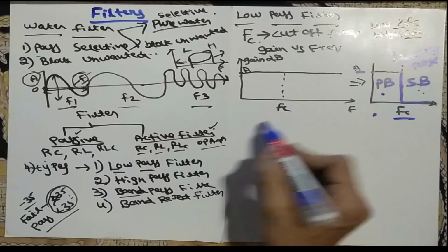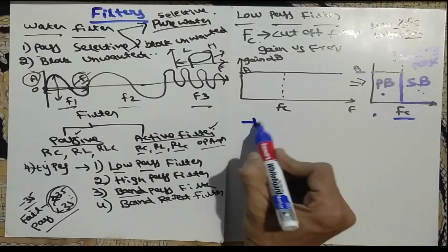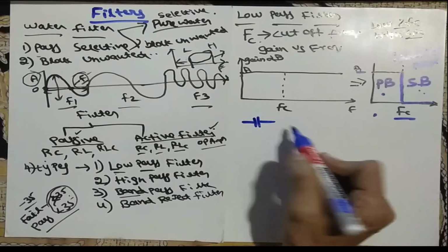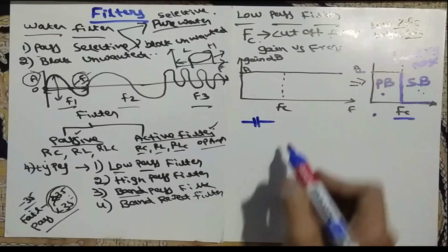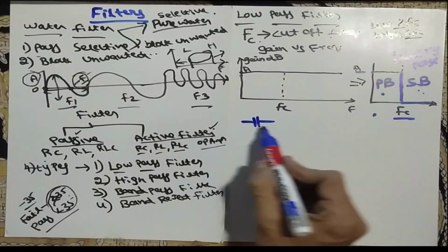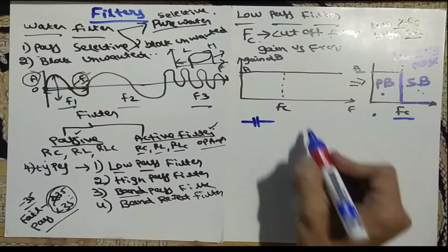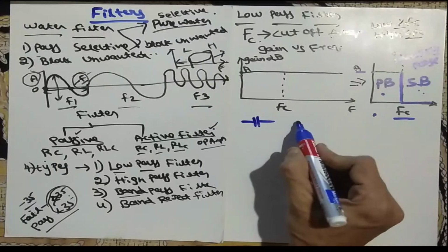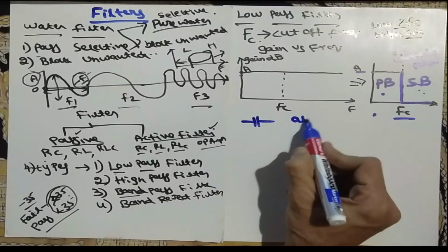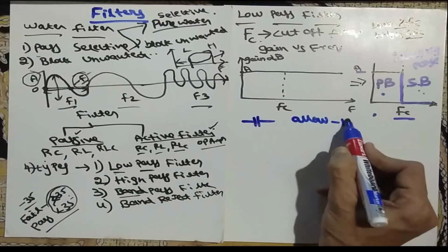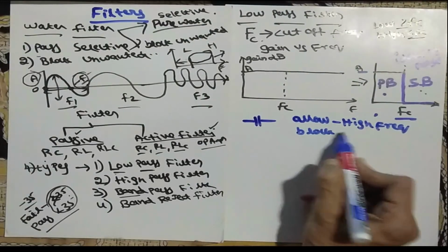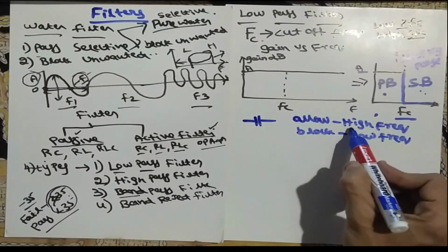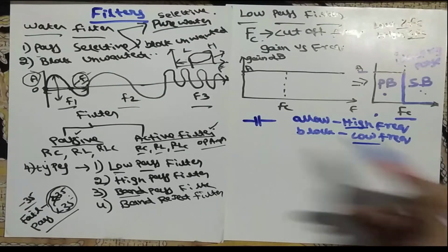Usually, if you take a capacitor, what is the operation of a capacitor? We know that in DC it blocks, and in AC it allows, but usually in AC it will not allow all the AC signal. A very important thing you have to remember is that a capacitor allows only high frequencies and it will block the low frequencies. So again the question occurs: what is high and what is low?